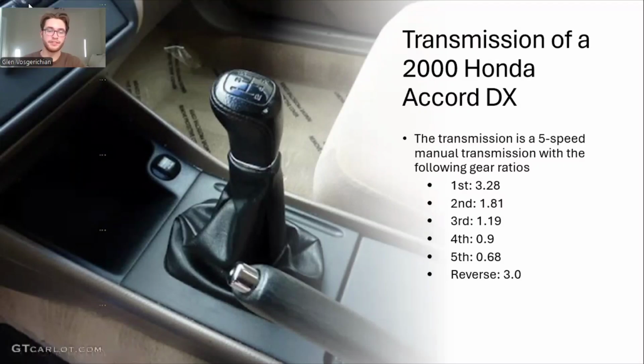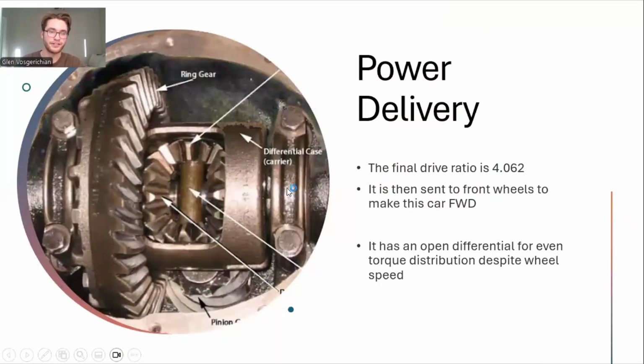Right, so first we're going to be going over some of the drivetrain specifics of the 2000 Honda Accord. And the first thing is our transmission. The transmission that I have in this 2000 Honda Accord is a 5-speed manual with the following gear ratios, as you can see. All right, and moving on. So after it goes through the transmission, it goes through the final drive ratio, which is 4.062, and then it is then sent to the front wheels.